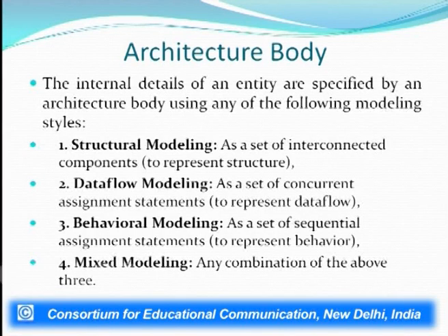It is important to mention here that the entity description is independent of the modeling style. It will be written in the same fashion even if any of the modeling styles is adopted, but the architecture will depend upon the modeling style that is being used. Accordingly, the semantics will change, which we will see as we see more examples down the line. Now, the first type of modeling is the structural modeling, which is basically a set of interconnected components, that is, it is going to be representing the physical structure.